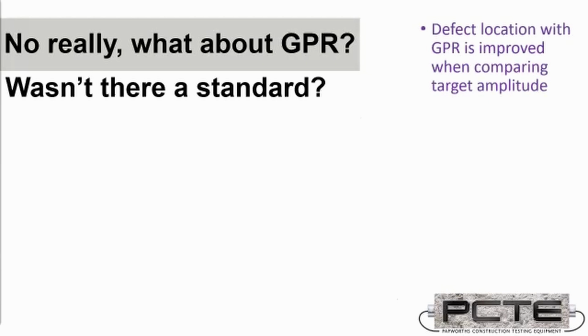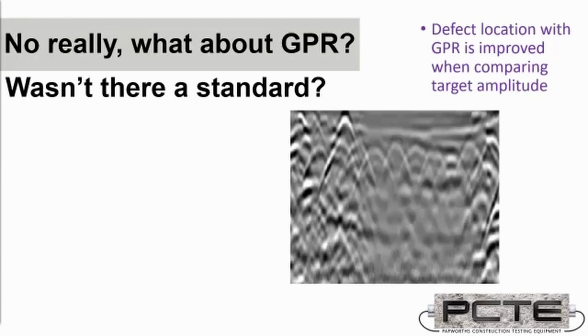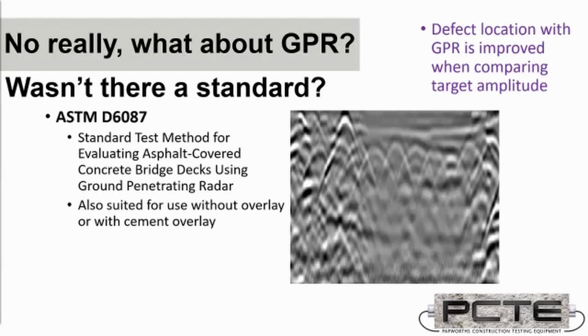There is a standard which relates to degradation of structures. The standard is ASTM D6087, standard test method for evaluating asphalt-covered concrete bridge decks with ground-penetrating radar. This is the quantitative approach I mentioned.